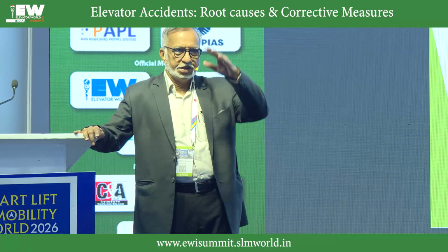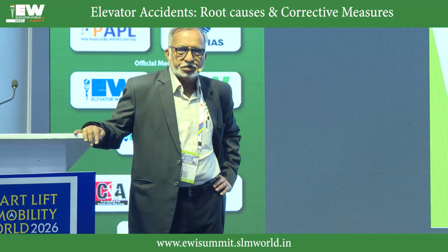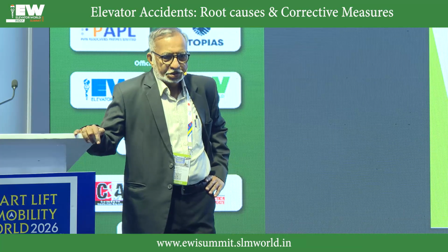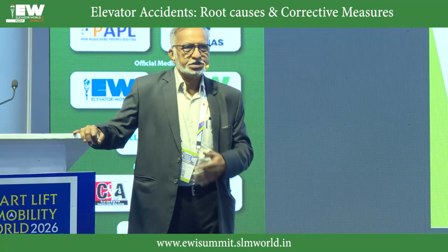This mainly happens when the lift is stuck between floors, halfway. Say the door height is 2 meters and the lift is stuck at around 1 meter; then this possibility is more. If the lift is stuck just before approaching the floor, then also it is possible. But for that, we studied the door apron in an earlier session. The door apron covers the gaps, so there is less possibility of a person falling into the lift.